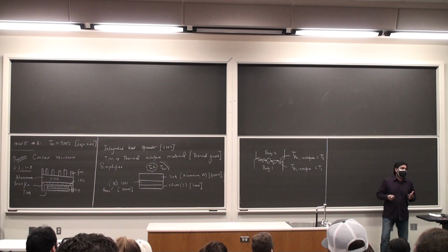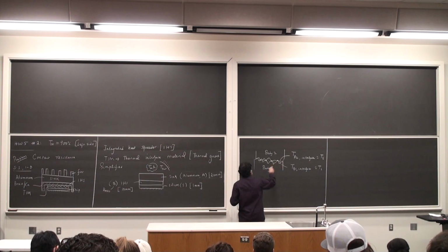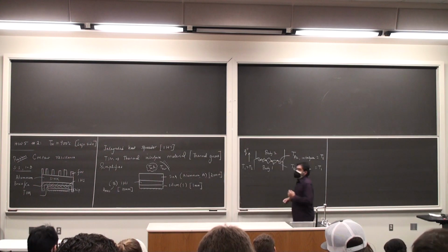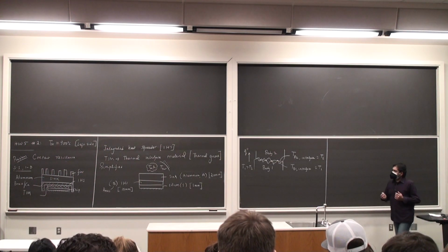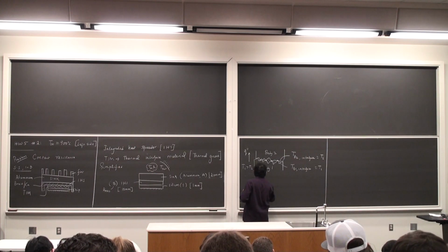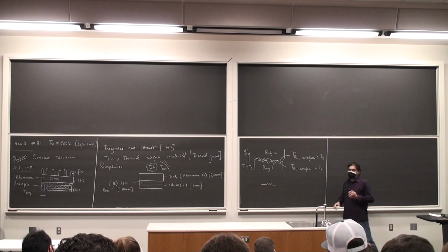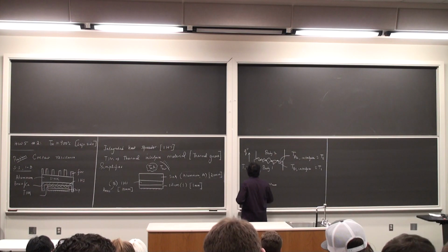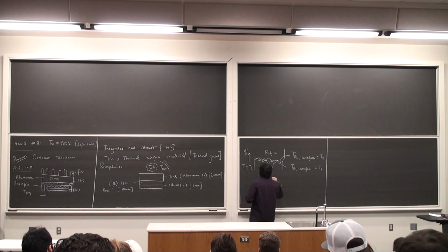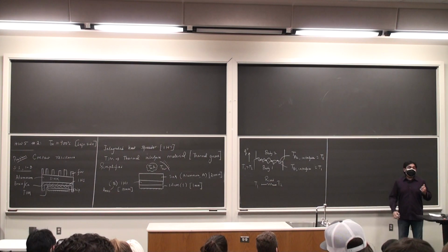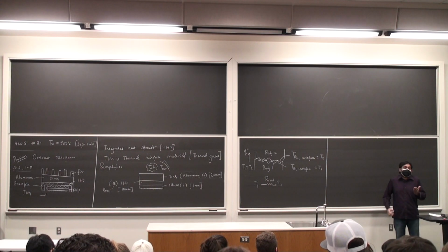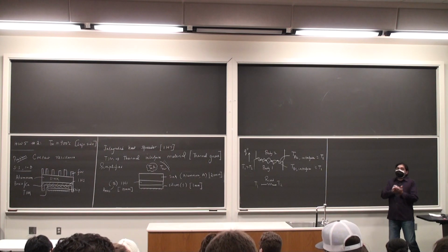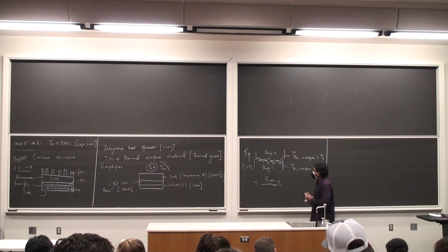Okay, so one is, let's say that T1 is greater than T2. This is the path of heat flux, okay, passing through. If T1 is greater than T2, if I write a thermal resistance network for this, there are two possibilities. Okay, one is I will have conduction at the point of contact between body 1 and body 2. Okay, so this is T1, this is T2, there is our conduction. They could be dissimilar materials, which will make it much harder for me to use any kind of a formula, because I don't have a formula for when two dissimilar materials contact with each other. What's the conductive flux, right? I have to make use of one and the other and do an energy balance and so on. So we can do that.